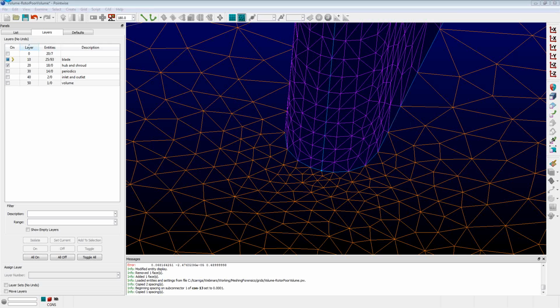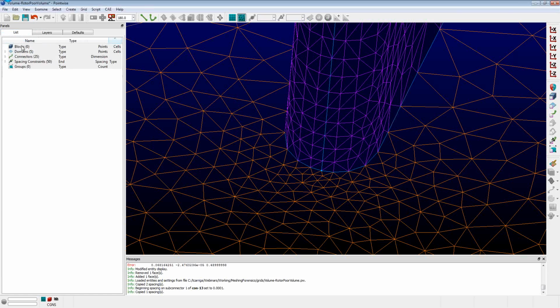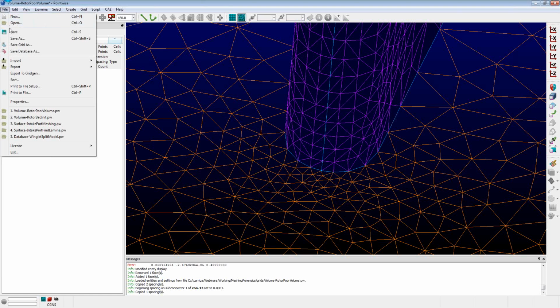Now, when generating prism layers, if you run into collision issues, what is the first knob to turn? That's an excellent question. When you're generating a T-Rex mesh and you have a collision, the knob that you want to turn in that case is the collision buffer. Now, I don't have a block available right now, but the collision buffer is in here. Let me pull up something we can look at.